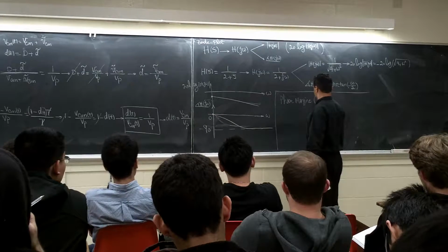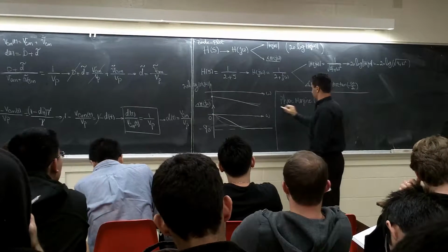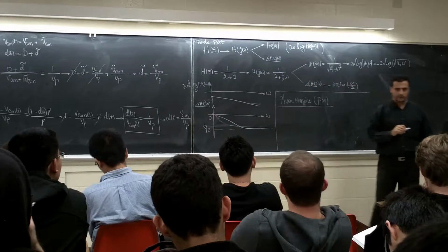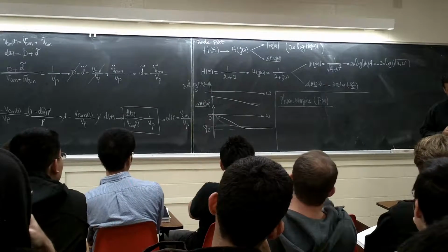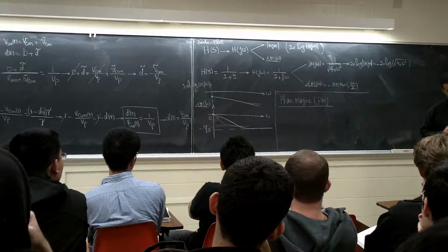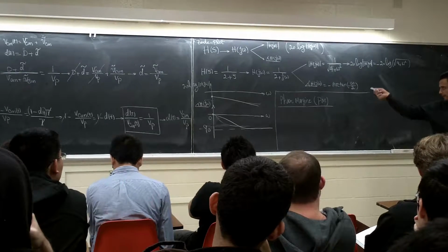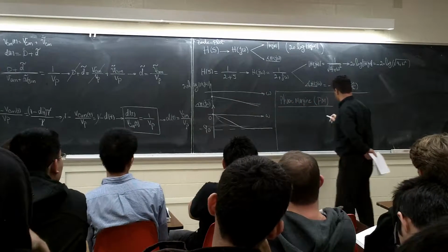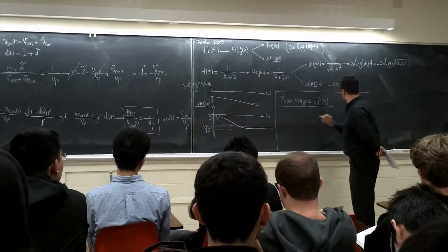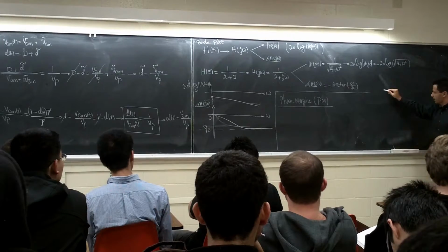Anybody, can anybody remember what the phase margin is? The difference between the phase and minus 180 degrees when the magnitude is 0 dB, when this one is 0, right? Let's say if we have a, can everybody see? I'm going to put it here.